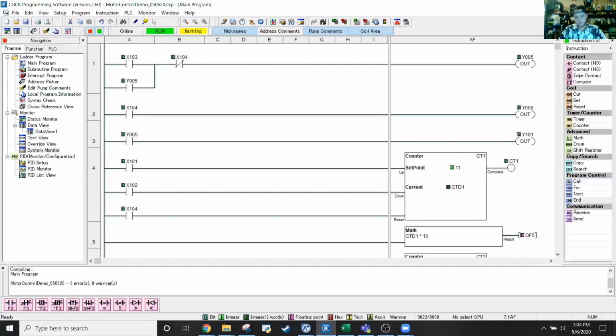And the value last time we did this last quarter was really close to what it should be. But that's why those encoder modules need a special input card to take the encoder input, and those are configured specifically so that they don't have that problem of the scan time not picking up the signal. So, cool, that is a really good question.